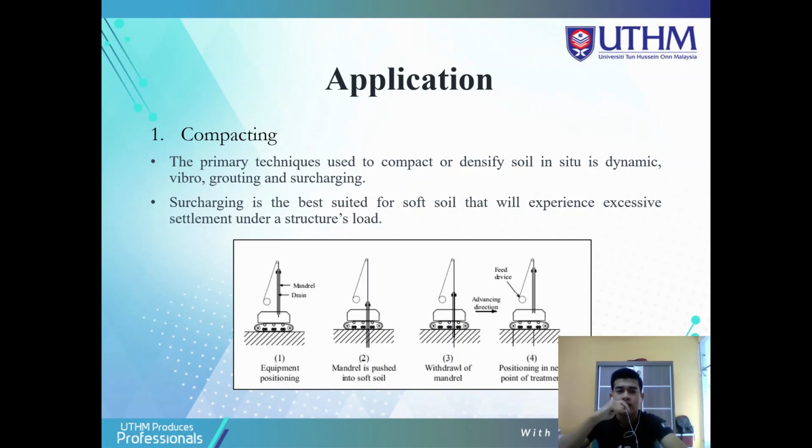Vertical drains are placed prior to surcharge placement, which accelerates drainage and reduces surcharge time. Typically, 1,000-foot long rolls of drain are fed into a mandrel, which is pushed, vibrated, driven, or jetted vertically into the ground through a mast mounted to a backhoe or crane. Then a dump truck is used to transfer fill soil utilized for preloading, and dozers are used to push the soil into the mound.